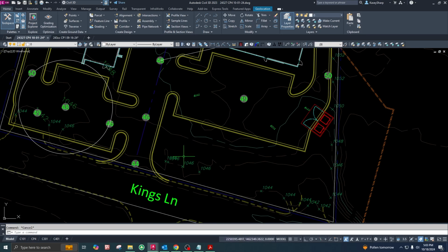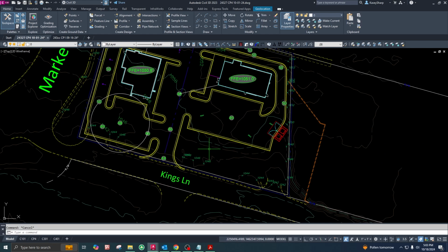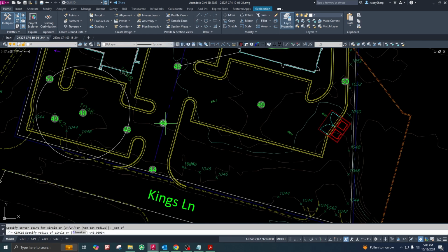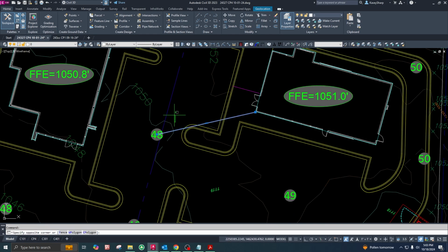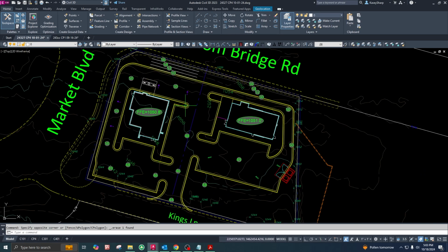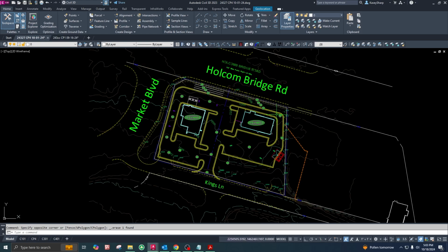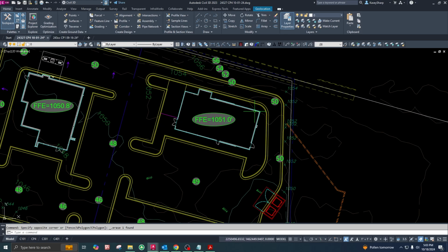And this area over there might be room to fit another development, might not be. But we'll just drop in some more spots over there. So we can just use these circles and use some quick slope calculations and these blocks to drop in conceptual spots. We're going to have a pretty steep slope here up on the north side, just to flatten out our actual working area as much as we can.